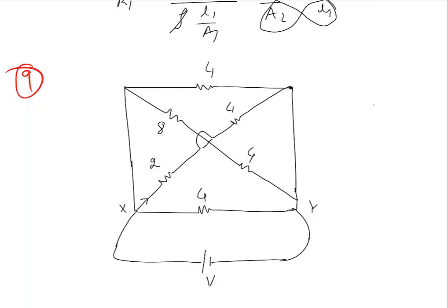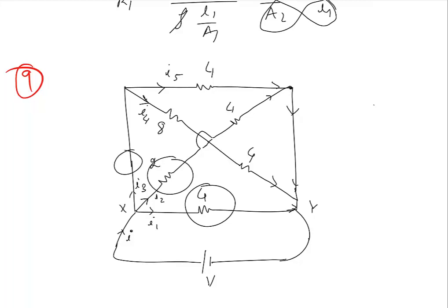So you can say this and this and this are parallel connections, so here I1 will go, here I2 will go, here I3 will go, and I1 plus I2 plus I3 is equal to I. Now if you see again, I3 is getting diverged into I4 and I5, and then all of them are meeting together at Y. This says a simple thing. It says that first these three were in parallel, and then out of this, 2 more parallel connections arise. So this question becomes quite simple.